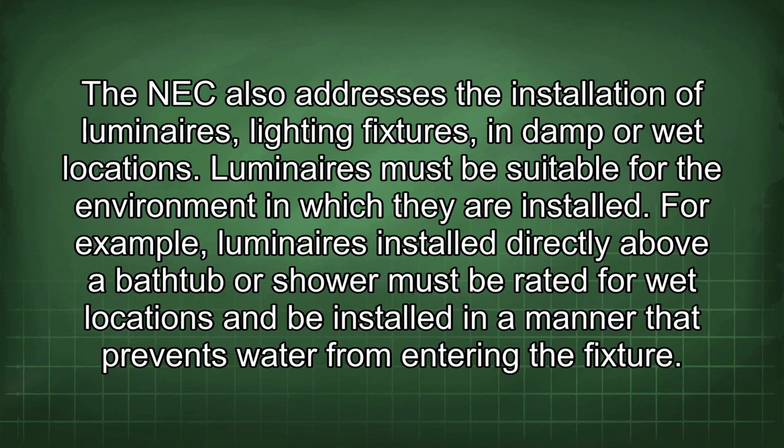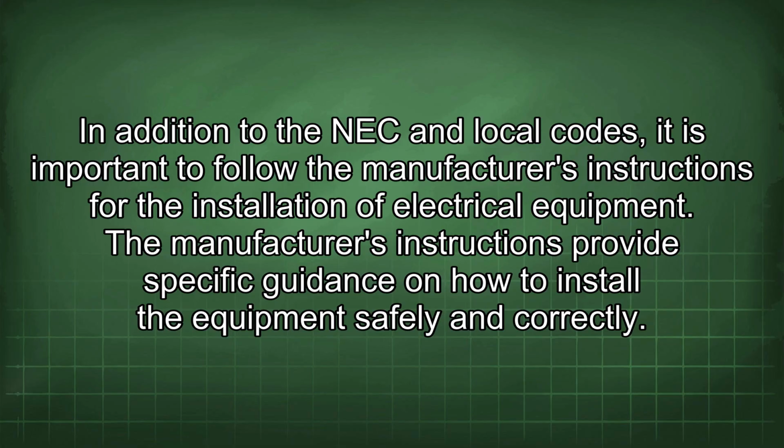The NEC also addresses the installation of luminaires, lighting fixtures, in damp or wet locations. Luminaires must be suitable for the environment in which they are installed. For example, luminaires installed directly above a bathtub or shower must be rated for wet locations and be installed in a manner that prevents water from entering the fixture. In addition to the NEC and local codes, it is important to follow the manufacturer's instructions for the installation of electrical equipment. The manufacturer's instructions provide specific guidance on how to install the equipment safely and correctly.